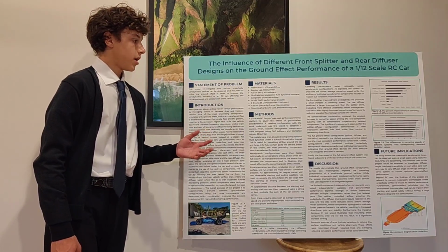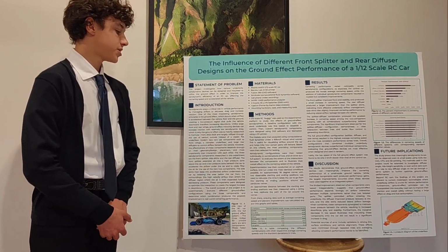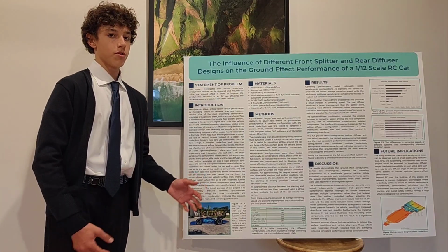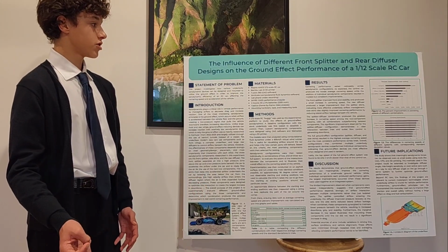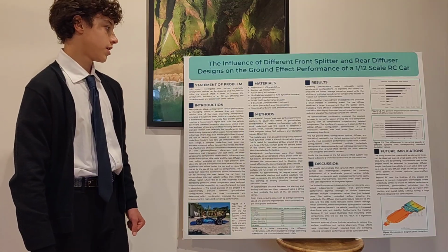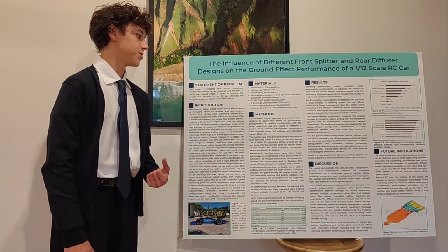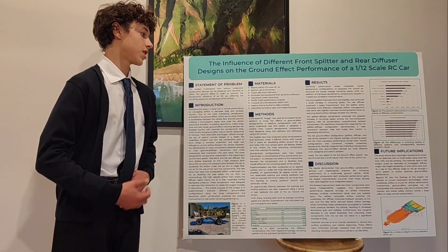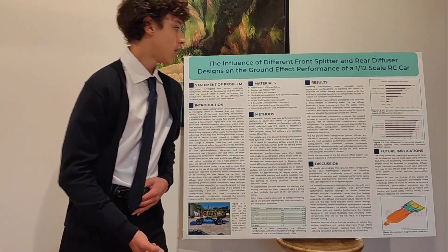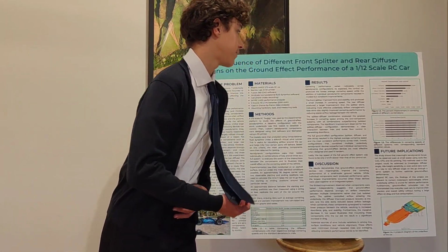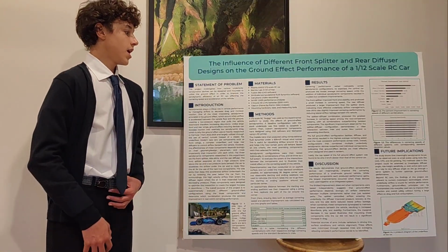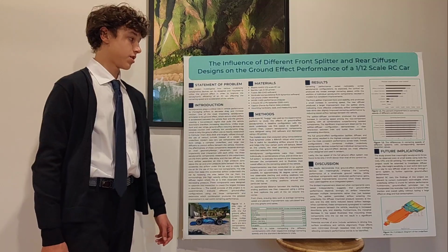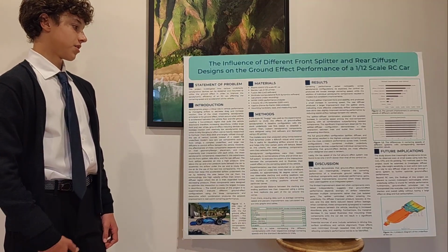Now, the baseline car produced the slowest average cornering speed. The single part combos produced marginal increases in cornering speed, but they were nothing noticeable compared to the 2-part combos and the full system, with the 2-part combos having a larger increase in cornering speed, somewhere around that 15 to 16% mark. And then the full system was able to reach a percent improvement of 24% over the other combinations and the baseline configuration.